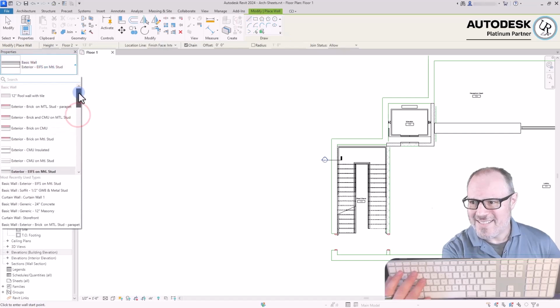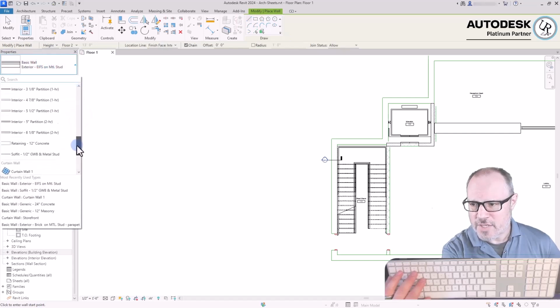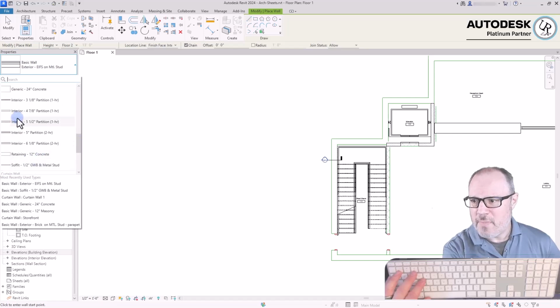These are all of the existing wall types inside of this current project. They are organized by description based on their typical use. We have soffit wall, retaining wall, interior wall type, generic wall types, foundation wall, and exterior wall type. We'll look at the construction of the wall type materials in a moment. The description of the wall type is merely a notification of what the wall is typically used for in the condition. You can label the wall type anything that you wish.